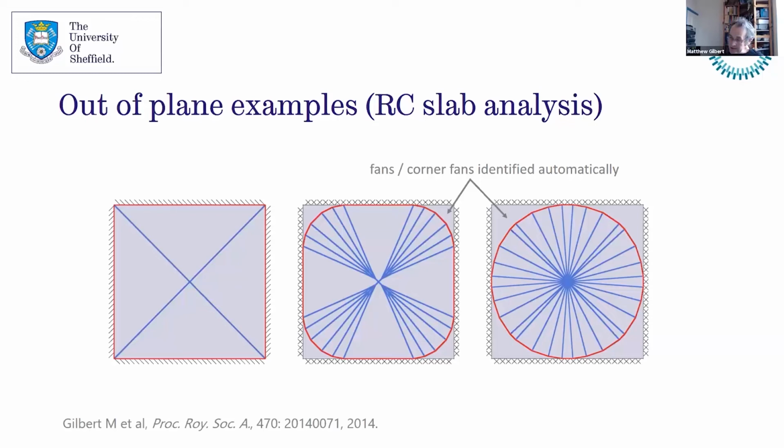And that's something that's really useful, because the traditional yield line method had fallen out of favor a bit because A, manual calculations are becoming less popular, but B, there was a real concern that if you missed the critical yield line pattern, then you would end up with an unsafe prediction of the strength, and hence you would potentially run into a safety problem. So this basically systematically automates the yield line method for slabs.